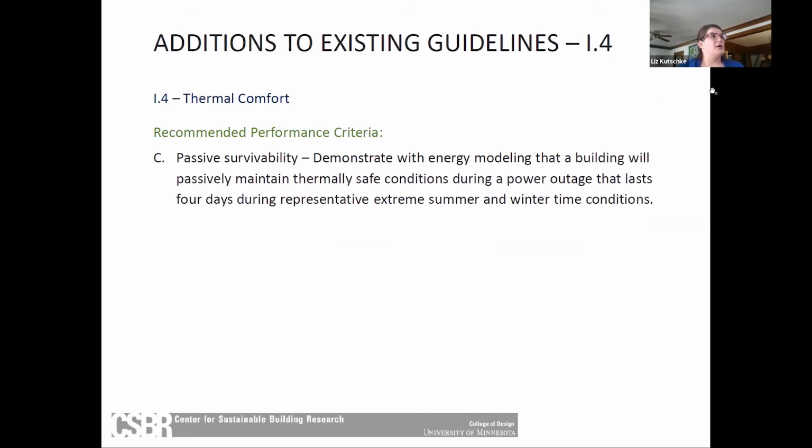Another additional one is to I4, which is thermal comfort. So the basic concept here is of passive survivability, and that would be that the building can maintain a thermally safe, not necessarily comfortable, but thermally safe conditions during a power outage lasting 4 days during representative extreme conditions. So that has a lot to do with the insulation of the building and the way it holds on to heat or cool throughout time. So that can be simulated with energy modeling, and that's what we would want to see for that requirement.